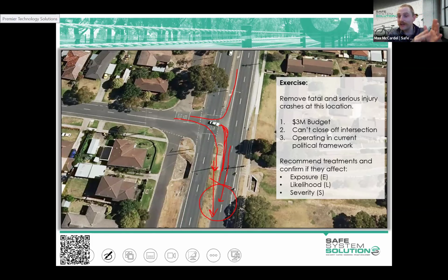But generally, the impact speeds and impact angle work quite well with seagull treatments. The disbenefit associated with the seagull is that kind of merge is really uncommon and it's also hard to do. If you were doing that right turn, you need to look over to your left to see there's a gap in traffic, which is super uncommon.